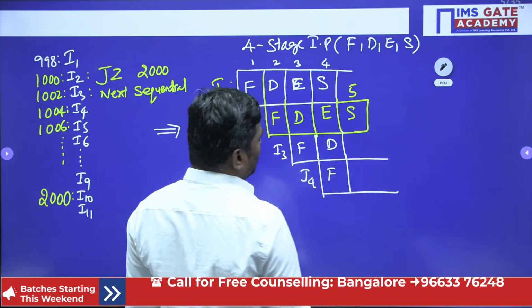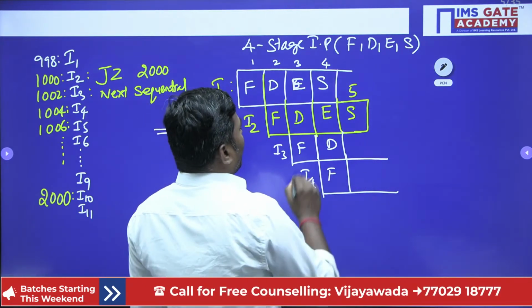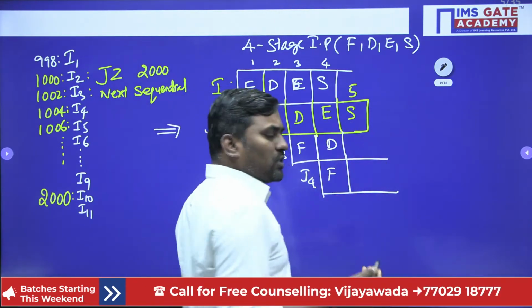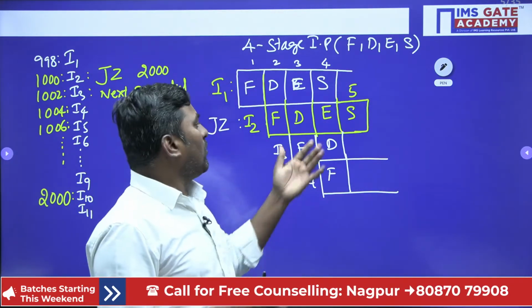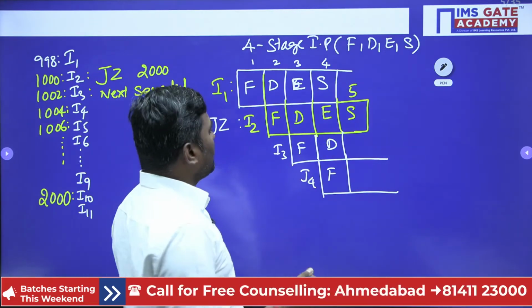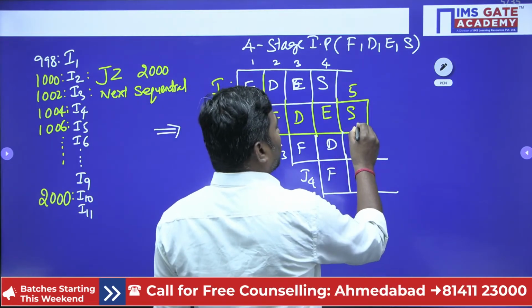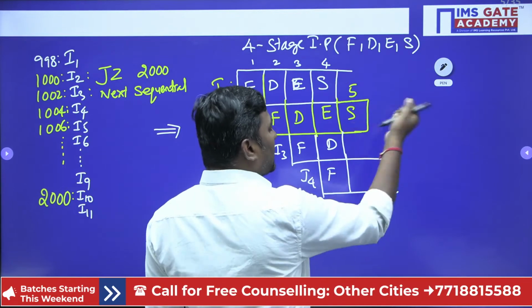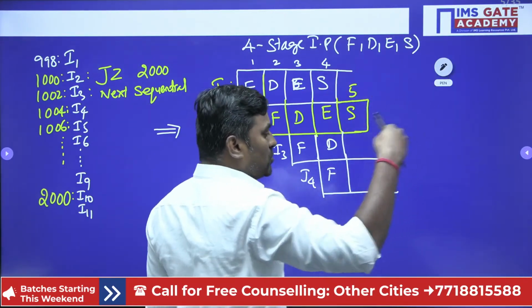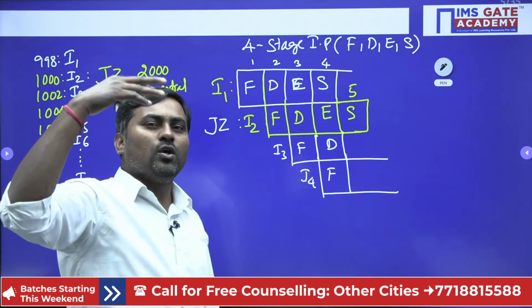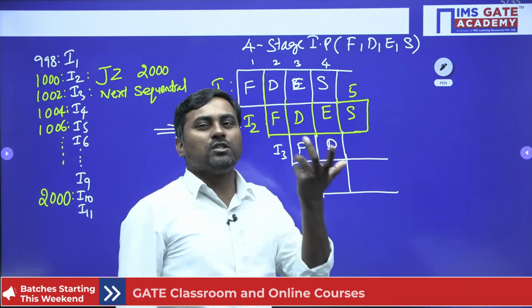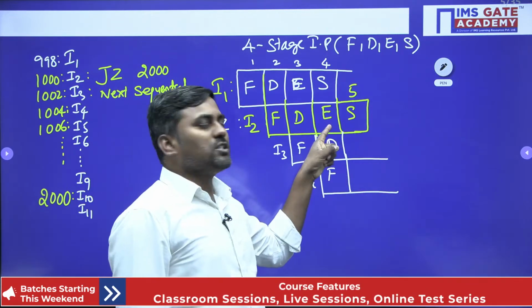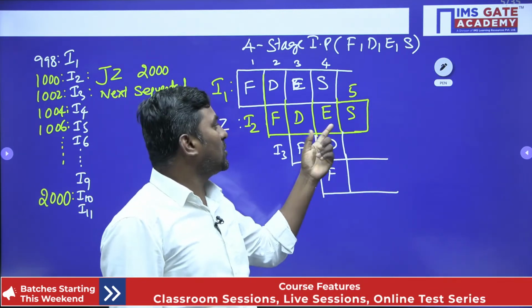Execution of the branch means verifying whether the condition is true or not, and the address will come at the end of the fifth clock only. When you are storing, generating the address, you have to place it into the program counter. So at the end of the execution stage, the results come out.